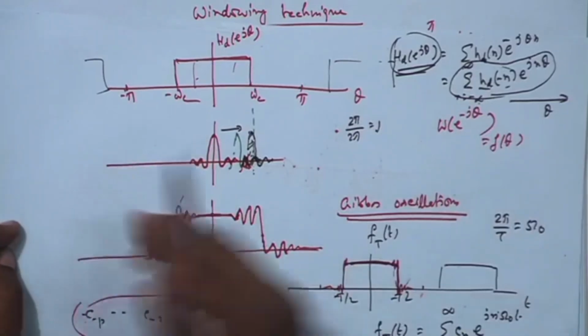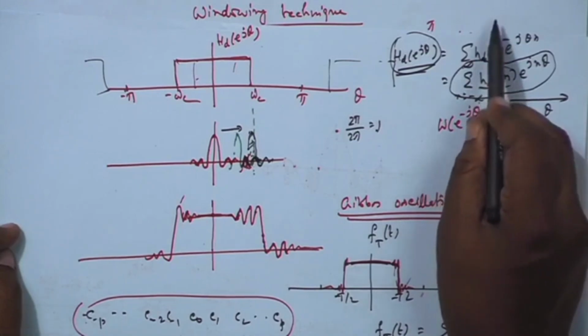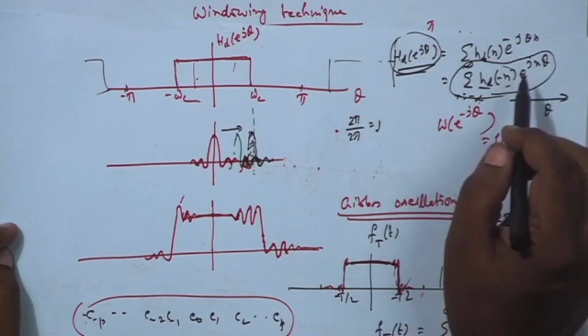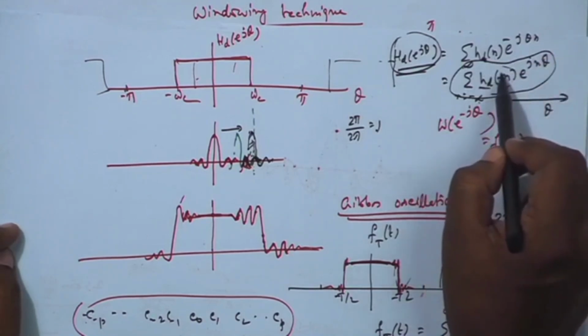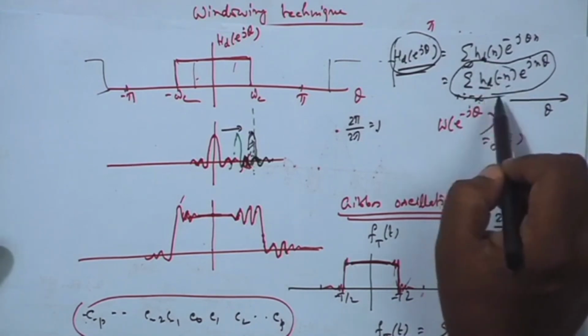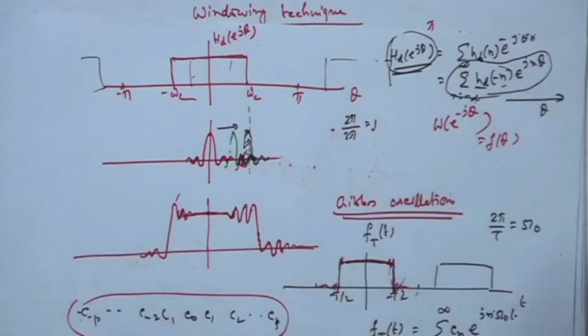Now, in this filter design, from this desired response h_d[0], h_d[1], h_d[2] and all that, h_d[-1], I am selecting only a few, h_d[0], maybe h_d[-1], h_d[-2] like that, a few of them, and I am throwing away the others.